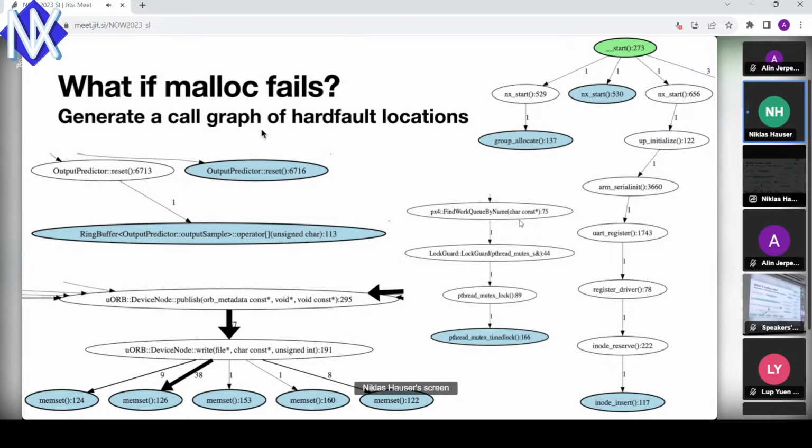That's just one example. We also have logic analyzers attached that try and inject failures, and then we see, okay, what actually happened here? Like if an SD card write, for example, failed, does that actually cause issues, or is the error recovery working properly? Unfortunately, all of these tools require the CPU to be halted. And if you're writing an autopilot, you're typically flying in the air. And so if you try and halt a drone in the air, then you tend to crash.